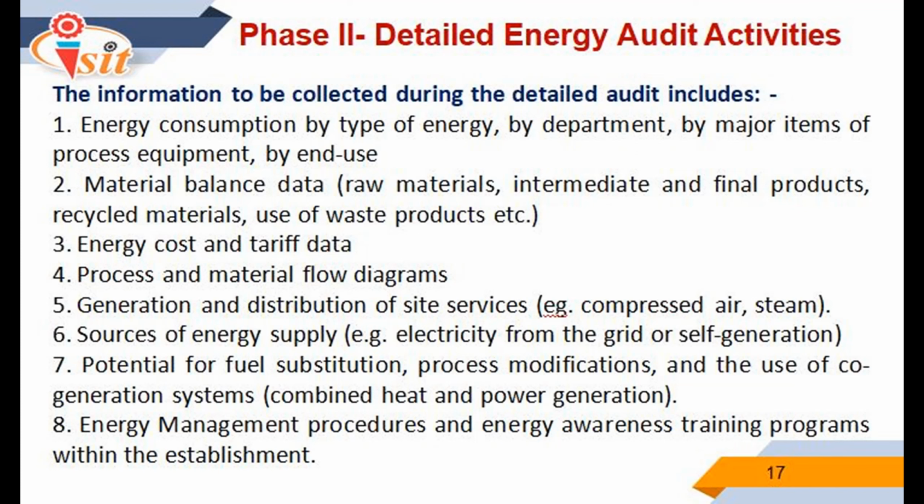Detailed studies to establish and investigate the energy and material balances for specific plant departments or items of process equipment are carried out. Whenever possible, checks of plant operations are carried out over extended periods of time, at nights and at weekends as well as during the normal daytime working hours, to ensure that nothing is overlooked.